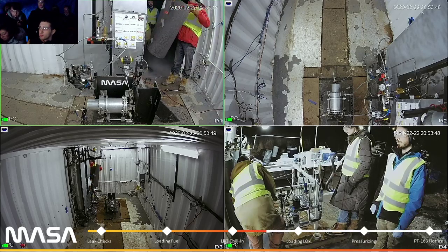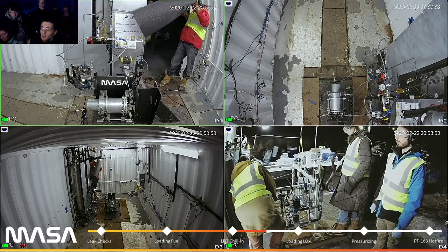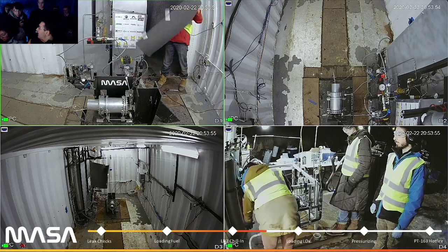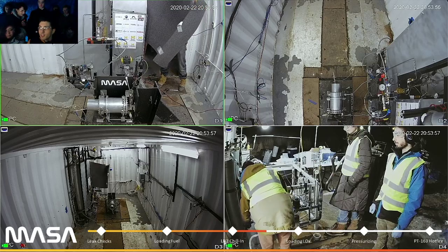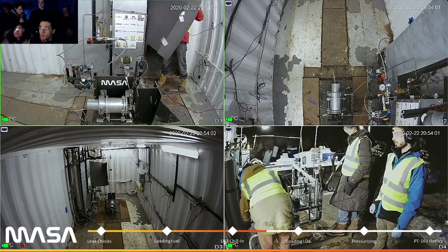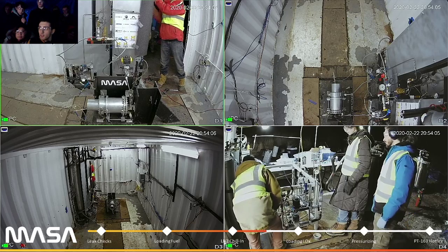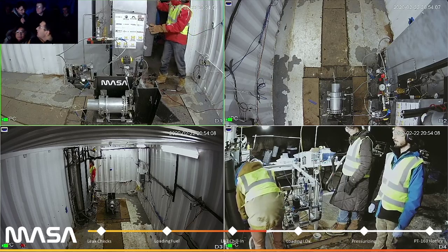Also, Ben is asking if we can ship him the engine. You think we can do that? Ship him the engine and do an igniter, bigger feed system and try it hard. Now, what do you mean by bigger feed system? Like higher pressure feed system? Because bigger tanks wouldn't really change anything. It's about the pressure of the propellant that you're feeding in. Unless you work at a fancy company, in which case maybe you can hook us up with some pumps.